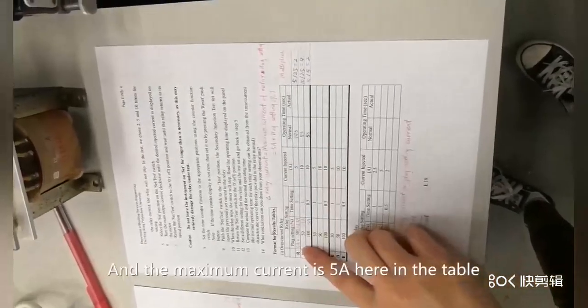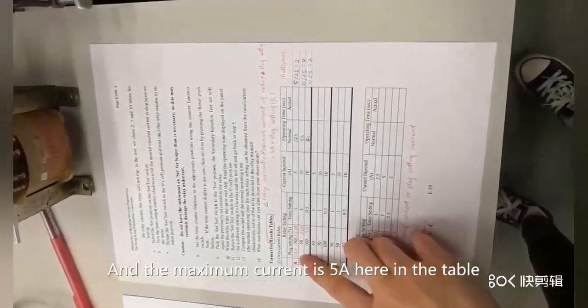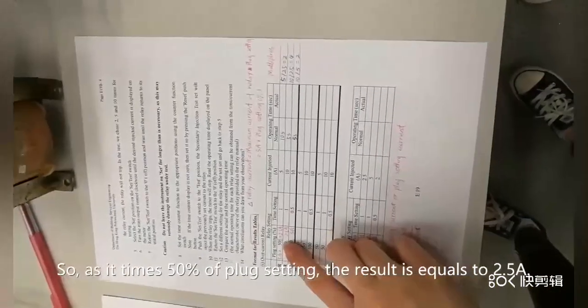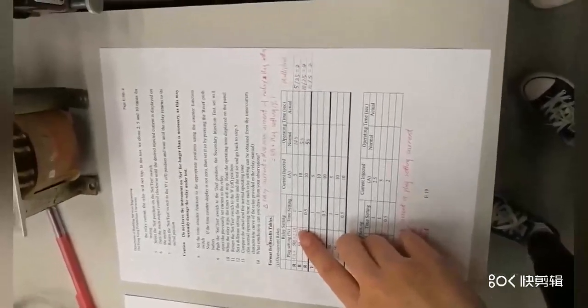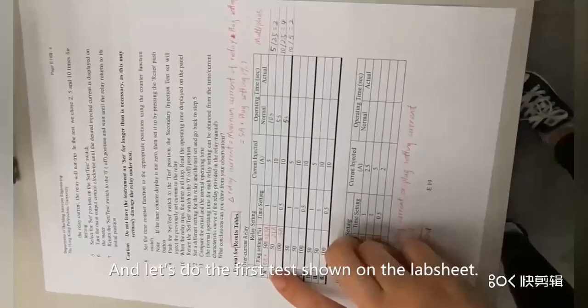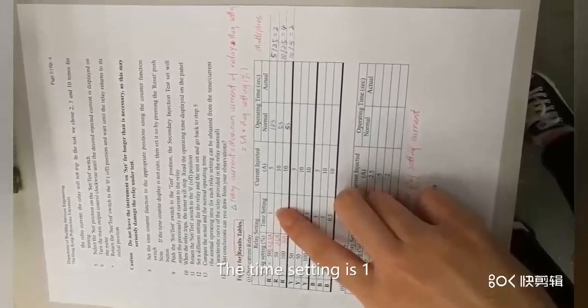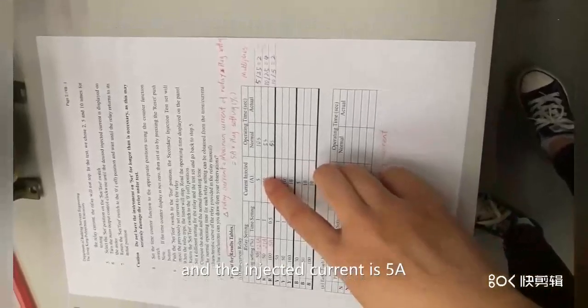The maximum current is 5 amperes, so a 50% plug setting equals 2.5 amperes. And let's do the first test. The time setting is 1 and the injected current is 5 amperes.